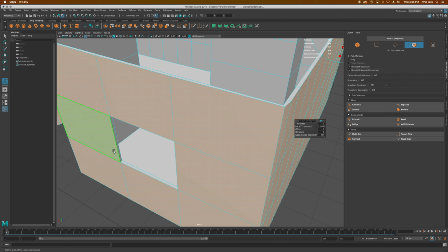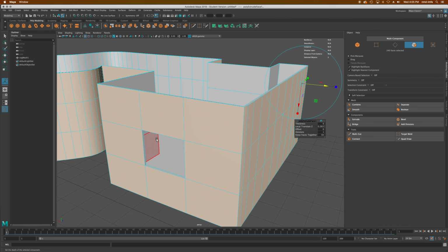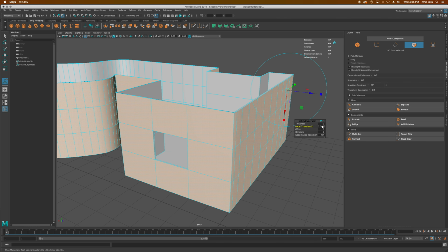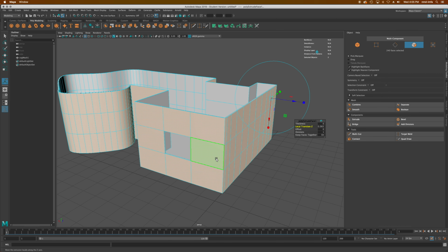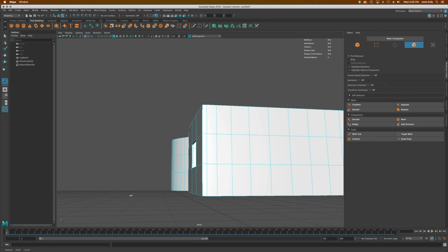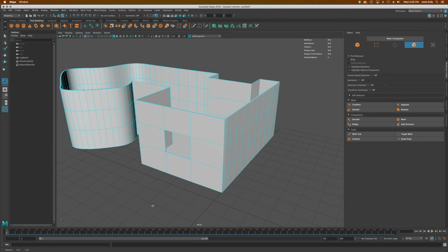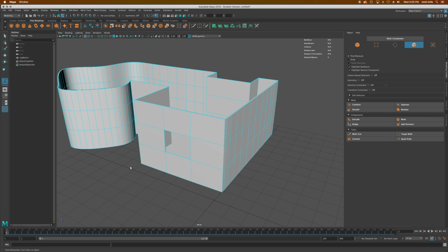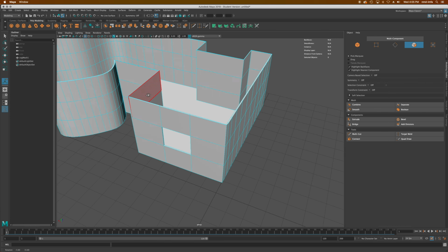So it's rough, it's not perfect. Again, I'm trying to figure out why I get these little bits of curvature around the edges when I do a full extrude like that. But overall, that's a very easy way to do it. I bring my floor plan in, I cut my windows, and then I extrude the whole building into the shape that I want. And if you're working with linear buildings, it's really easy to just do them one wall at a time. Sometimes these curved ones give you a little bit more of a challenge, right? So that's one way to do it.